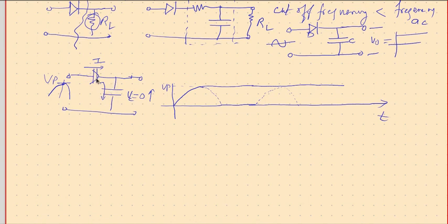It's going to remain constant under ideal conditions, but when you look at practical conditions, the diode, when reverse biased, we say it doesn't conduct, but that is the ideal case. In the practical case, because of some minority carriers available on the two sides, some small reverse current will be flowing, and that reverse current is going to discharge this capacitor. So there is discharge possible.